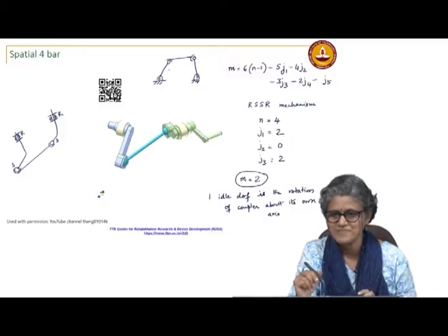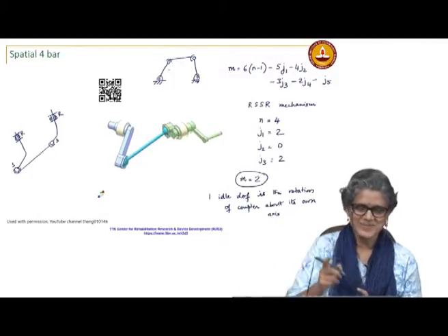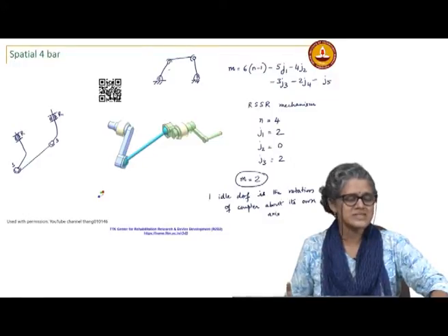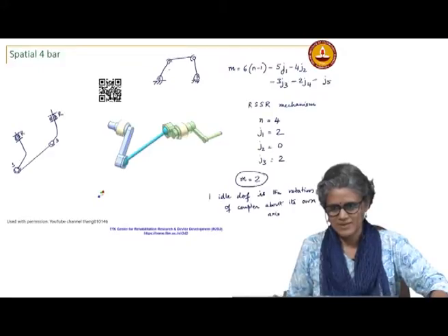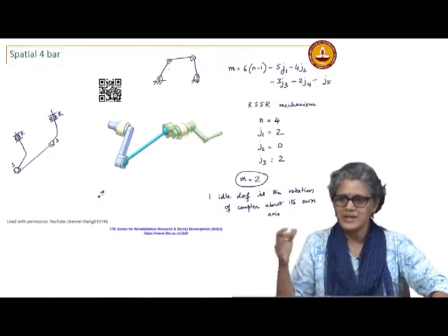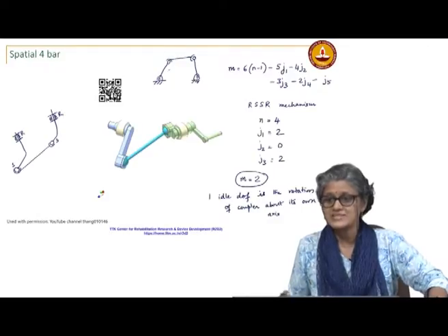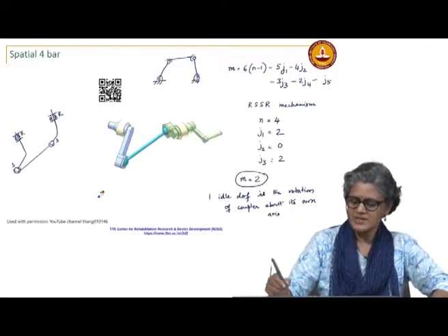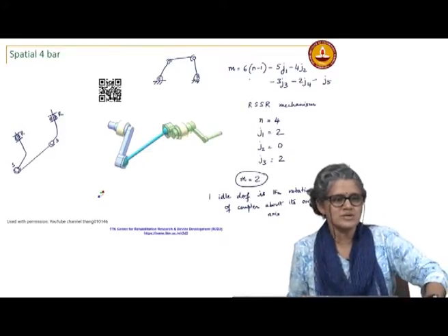Do you have a question? He applied this equation for a planar case. Ah, okay. I will let you think about that. We'll talk. Why doesn't this work? If I apply this for a planar case, it won't work, because you are applying the same constraint to multiple planar joints. So, they are not really independently taking off any. So, you will actually get something that is over constrained. 5 constraints on each and every independent link are dependent. So, the question here is, why doesn't this equation apply for a planar mechanism?